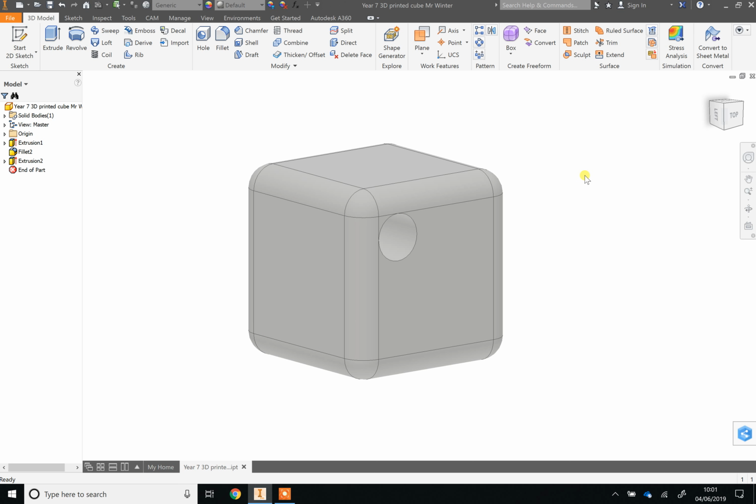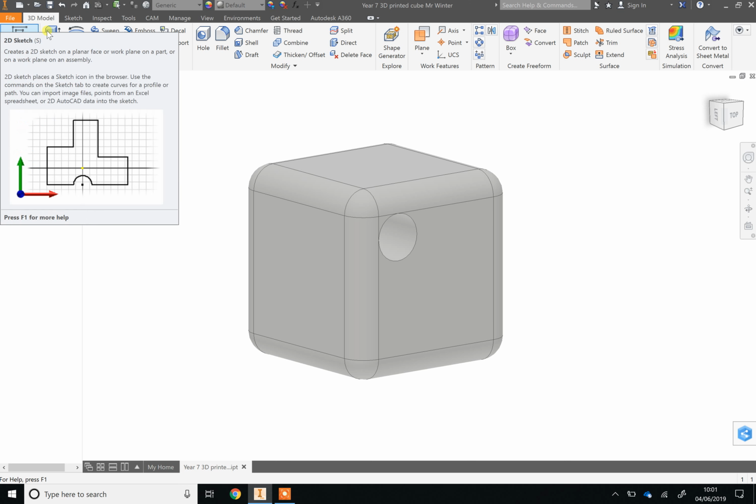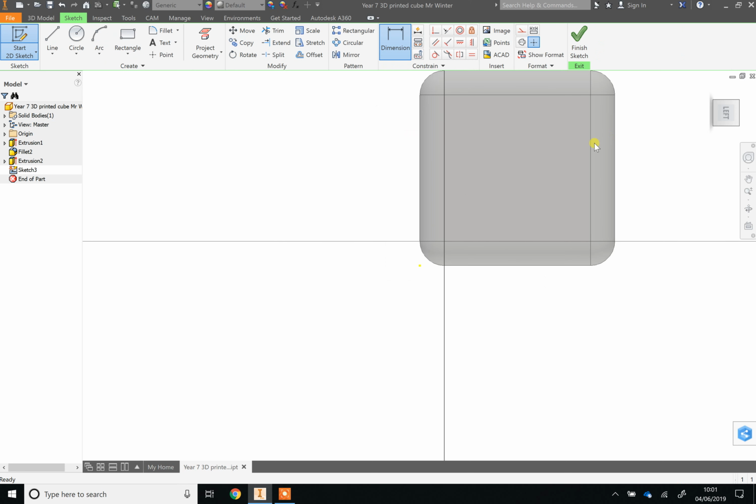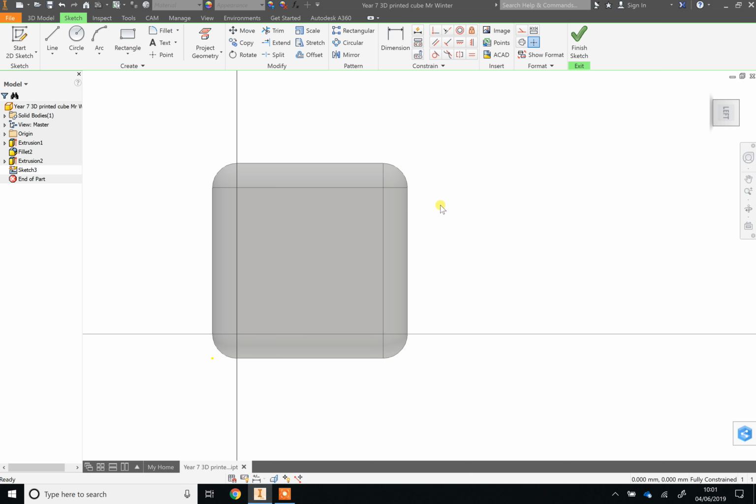So everything in 3D CAD starts with a 2D sketch. You draw it in 2D and then you extrude it into the third dimension. So go and make another sketch. This one you're going to sketch on this face here, the one at 90 degrees to that circle. So click on there. It will spin your view round. So if you were watching, our other circle's coming in here. So this hole needs to be in the top right now.